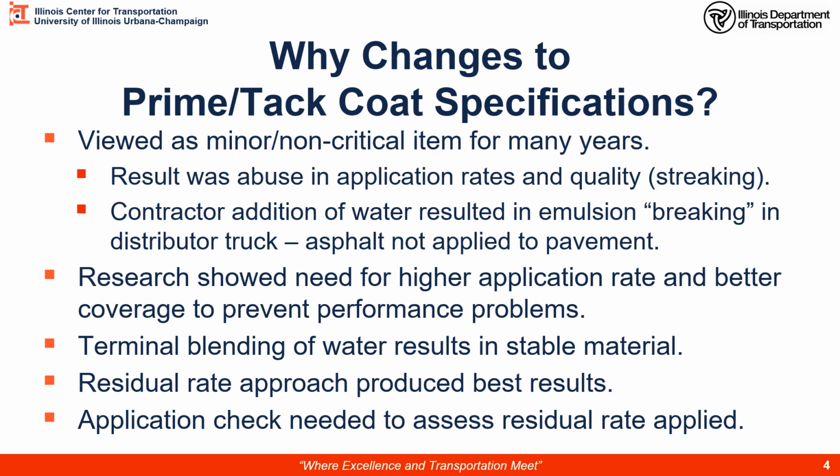And the hard asphalt was being left in the distributor truck that had to be cleaned out at the end of the year by the contractor. So we were paying for something and we weren't really getting it on the road. Quite a bit of research was done, and it showed the need for higher application rates and much better coverage to help prevent a number of the performance problems we've been seeing.